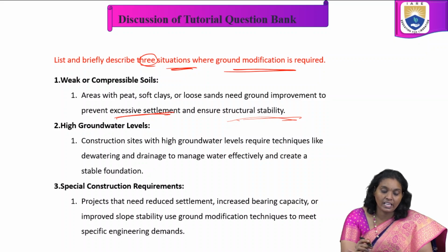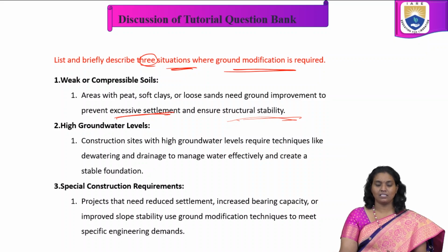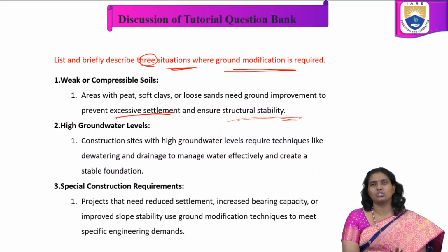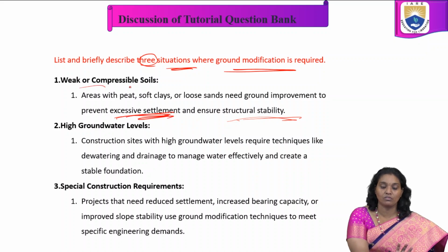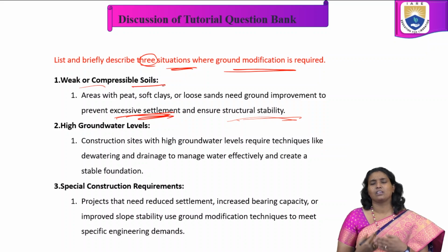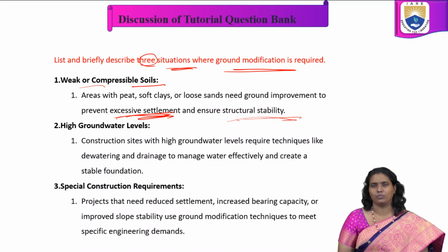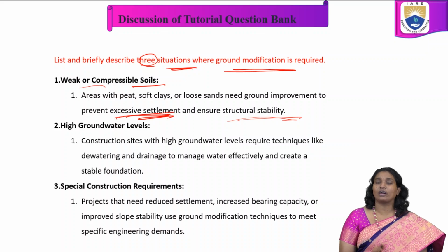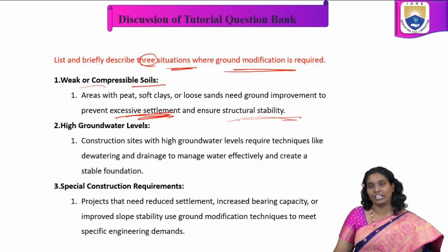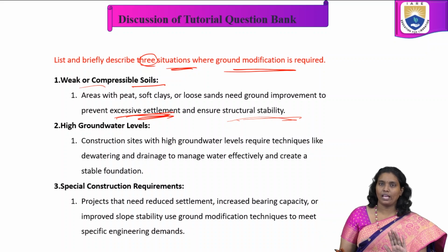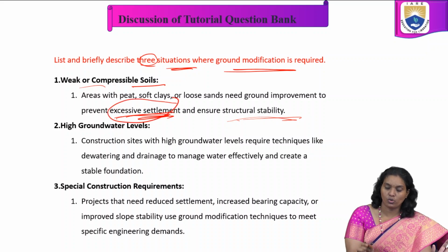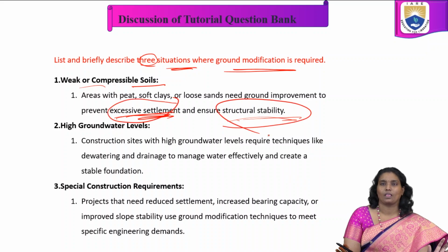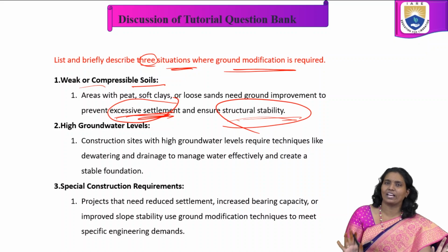So in weak or compressible soils, areas with soft clays or loose sands need ground improvement to prevent excessive settlement. In weak soils, from the soil parameter point of view, what is the problem we face and what we get based on the technique, that is enough. Based on the soil we are getting excessive settlement, and using a technique we are going to get structural stability. That's it. Please be confined.